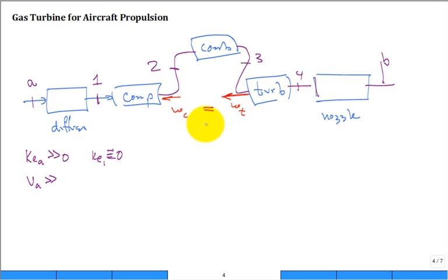The other thing is you've got to think about pressure. Now, we just talked about the pressure at the exit, B, compared to the pressure at the inlet, A. How does the pressure at B compare to A? Is it greater than, less than, or equal to A? They're the same pressure. And so you have to know that the exhaust pressure, the way the engine works, is just spewing out gases, but it's spewing them out at atmospheric pressure. The same pressure that's at the inlet to the turbine.